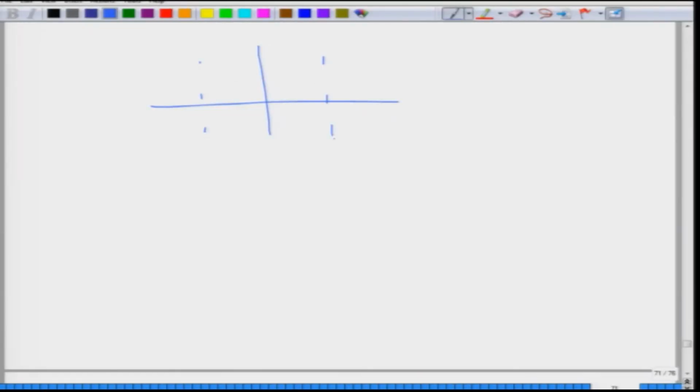So, I am again drawing this thing. Assuming that I am dealing with a fundamental mode, which would be of the form of a J0 function, you can come up to this part which is A, and then from here take off into the exponential thing. So, this will be K0 of gamma r, and this fellow will be J0 of kappa r. So, at r equal to a, these amplitudes should be equal to each other.